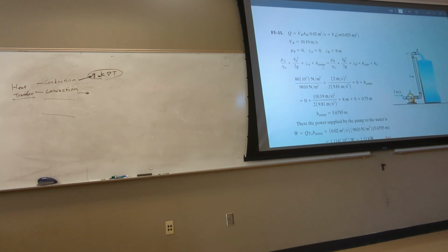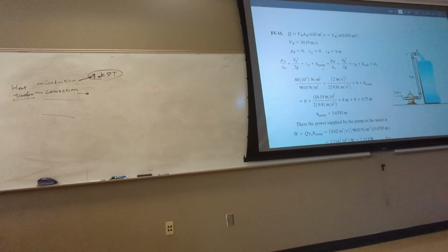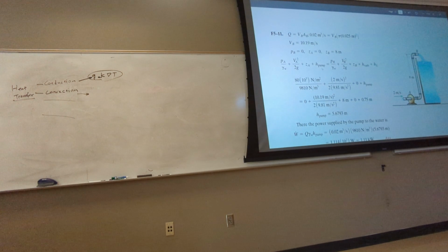And then H pump. Do I have the head of pump? That's exactly what I'm solving for. Right? So the good thing about the energy equation, you don't have to be creative. Like the momentum equation, you remember we did momentum, we have to be very careful what control volume, what are the inlets, what are the outlets, right? But for the energy equation, you just write it between 2 points without paying attention to what's inside the control volume. And it works miraculously. And it's just one equation. Momentum was 2 equations in 2D, 3 equations in 3D. Hopefully after this we come back to momentum differential.